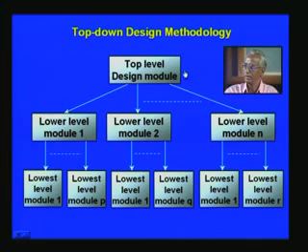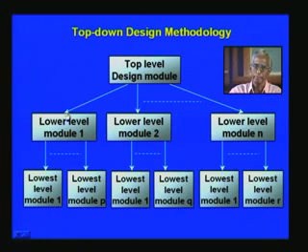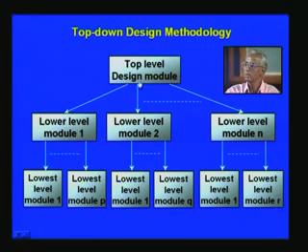If you have a bigger design, it is a good practice to downsize it to smaller sub-modules and further sub-modules in this fashion, and it can go any number of levels down. So the idea is that we manage only a small thing at a time. Once you have tested a small module, then you can put them together and test the higher module, right? So another method is the top down design methodology, where you start with the top level module, and here it will look like an ordinary IC with different IOs specified.